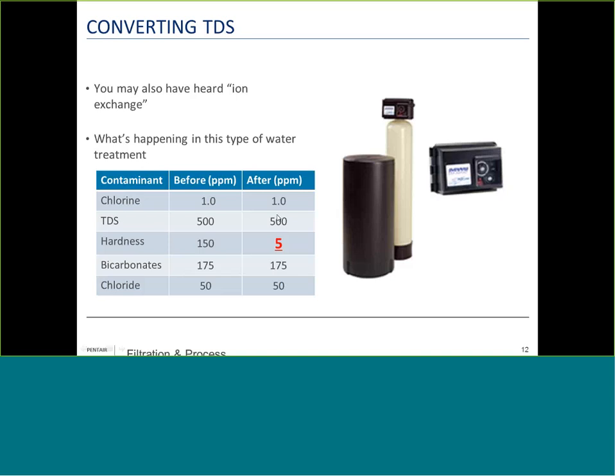Handling TDS, phosphate. The phosphate prevents scale from forming and does nothing for corrosion at the levels at which we can feed it for food service. At high enough levels, phosphates inhibit corrosion, but at the levels that were appropriate for food service, it will not. But before and after, if you notice, there is no real change in the water chemistry.